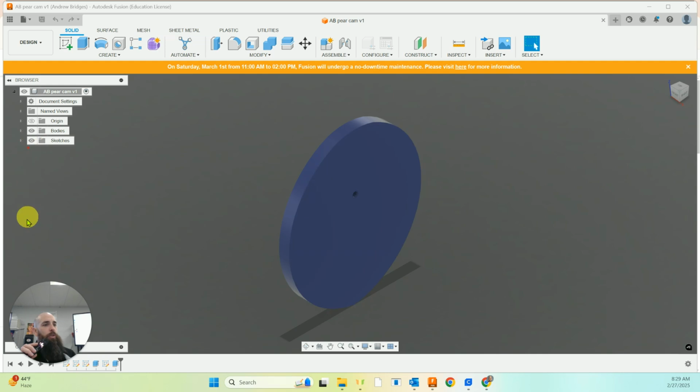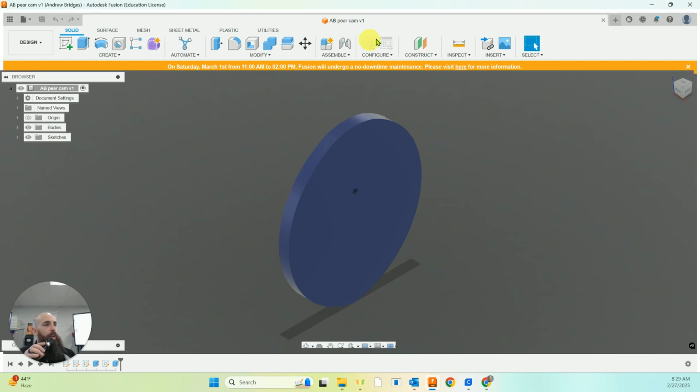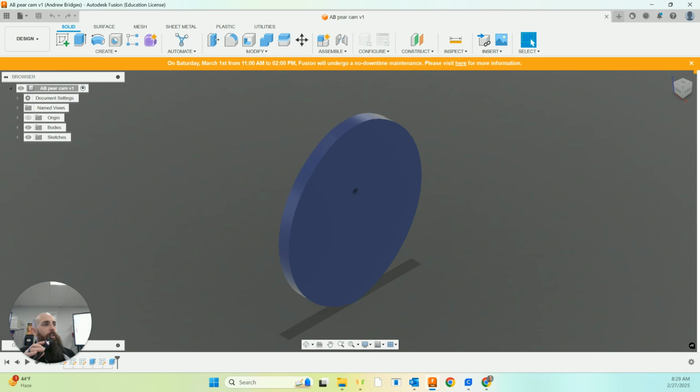Okay, we're going to first turn it into a DXF file, and to do that I'm going to come over here to my sketches and expand my sketches folder. It's not working for me. I got to move my toolbar out the way. I'm going to expand my sketches folder and come down to sketch 4. When I click on sketch 4, it only gives me the little circle for the hole in the center, and that's not what I'm looking for.